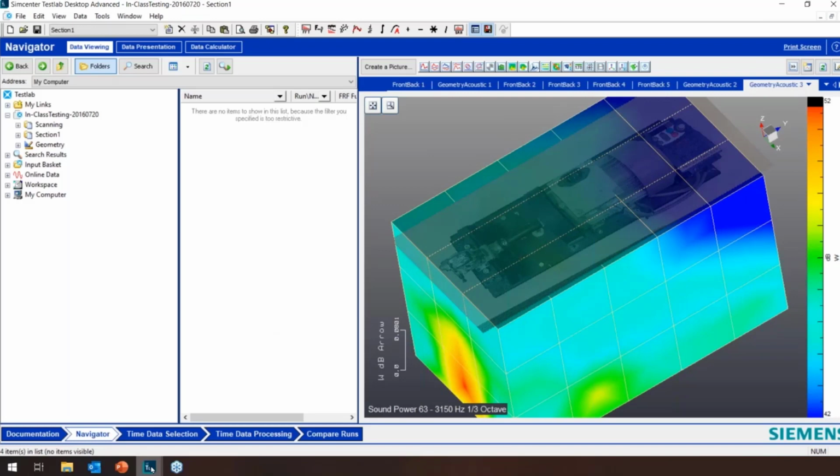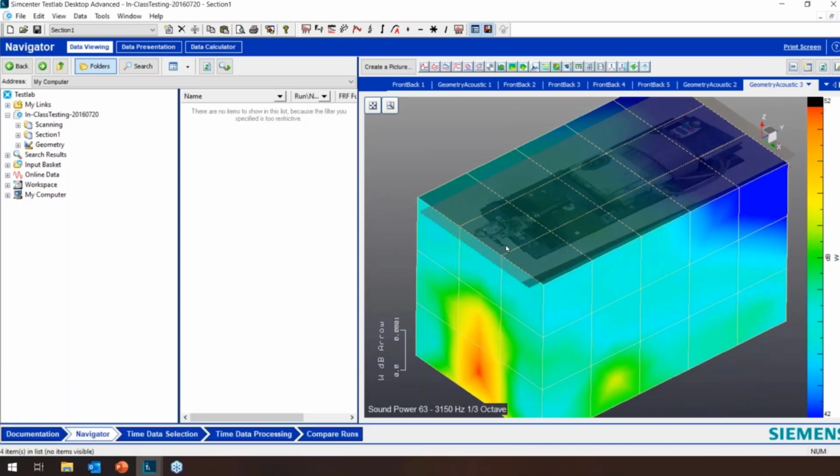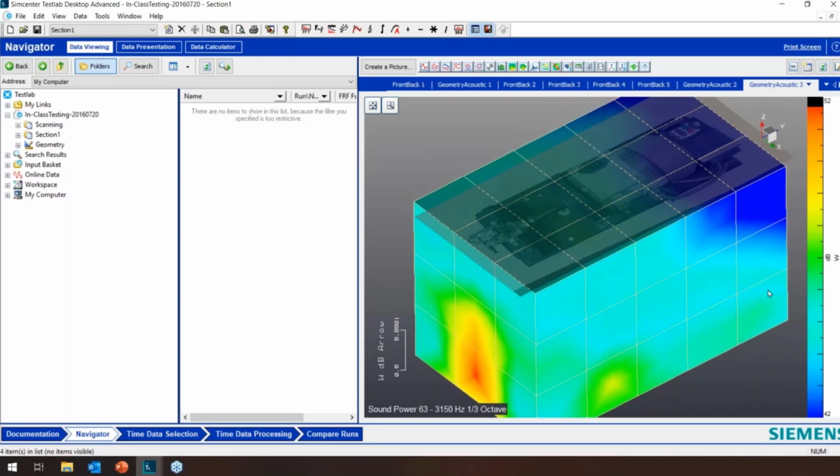So Steph, one thing which I wanted to mention was that with the PU probe, if you want to measure normal to the surface, you want to hold it vertically there. Oh, correct. Sorry. It is hard to see where I am on the screen versus the probe measurements. That is correct. So one comment regarding that, we did the discrete point measurements with the PU probe. We did point by point. There is the second ISO 9614-2 standard which governs the scanning method, and it requires that you scan 2 times, once along one direction and the second time orthogonal to that, right?